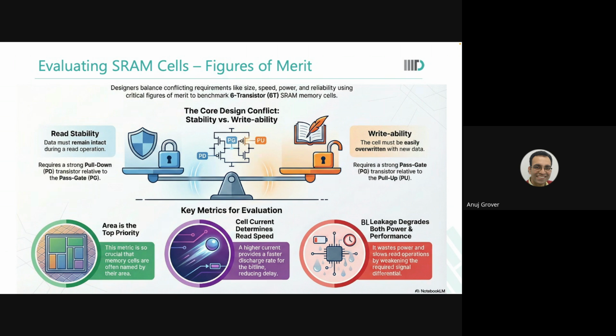They enter into a low power mode by pushing them into what we call retention. Retention means contents will be preserved, but leakage has to be reduced. How do we do that? We do that by lowering the supply level. Why? Because leakage is exponentially dependent on supply level. So if we reduce supply level, we will exponentially reduce leakage.